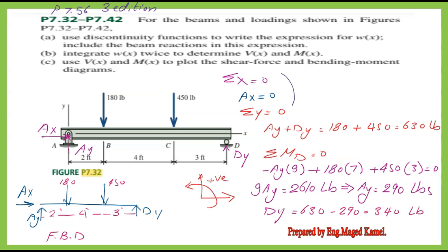In part B, it is required to integrate W of x twice to determine V of x and M of x. In part C, it is needed to use V of x and M of x to plot the shear force and bending moment diagrams.